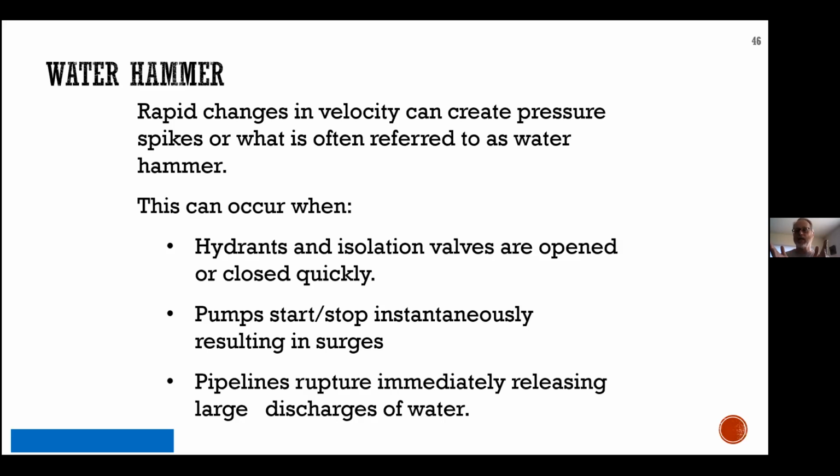And I was guilty of that once in North Van. We isolated a water main too quickly because of a break, and we split open an old cast iron pipe like a zipper, one full pipe length, so 4.5 meters of that old pipe. So we now have 2 repairs to do and a lot more damage. My superintendent was not very happy with me, but you know, you're in panic mode. This was in one of my early days as an operator, and we isolated the main too quickly.